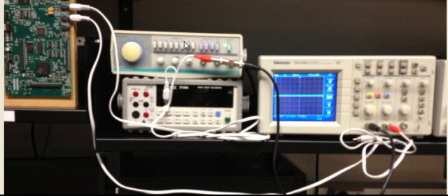When you switch to the low frequency, anything below 300 hertz, then you should be able to see that output and input are pretty much the same, maybe just a little bit of attenuation, because the filter always has an attenuation, and the filter that we designed is not an active filter, so you get some attenuation, but it is not a considerable attenuation. While, as we said, for high frequencies you get a lot of attenuation. Then this was the tutorial for the low pass filter.